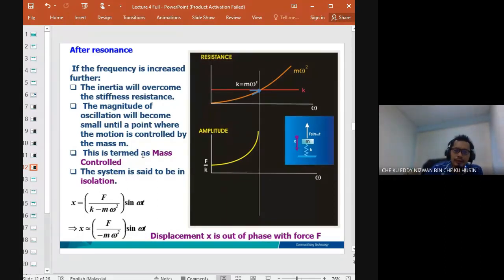So that's the dynamic properties if you excite with an operating speed greater than the natural frequency. This has been proved experimentally by a slow motion camera. After you keep increasing, it goes to the out of phase.